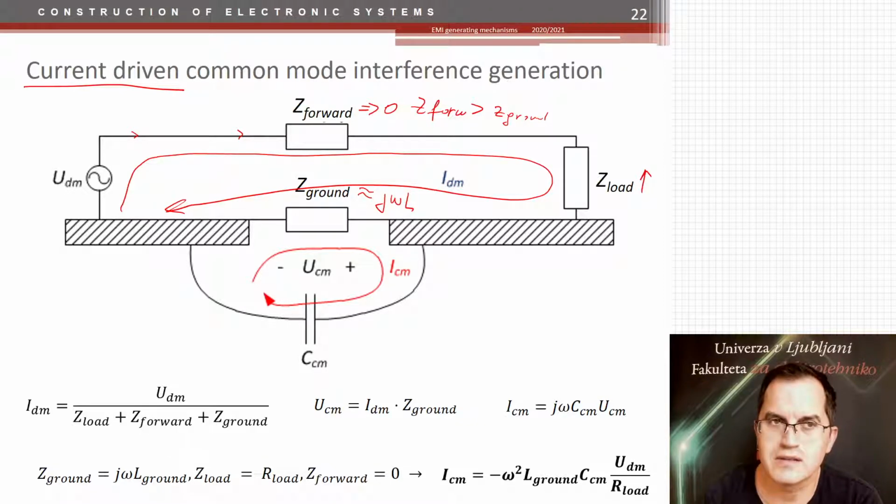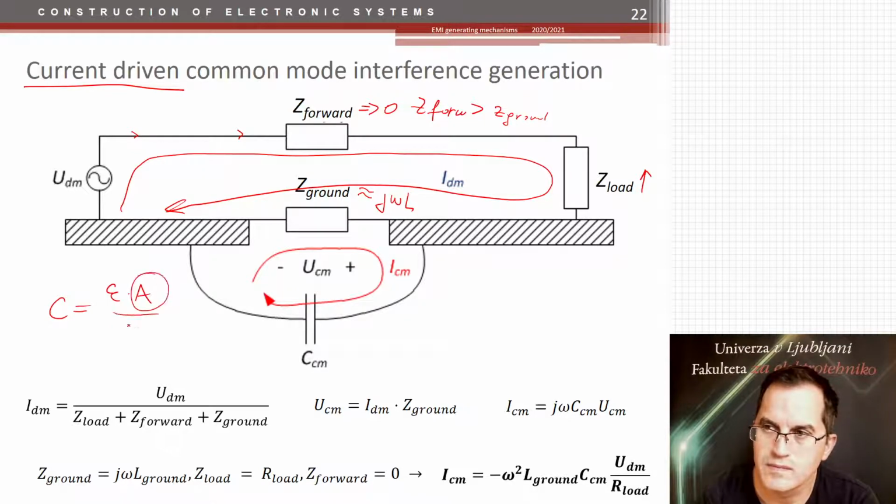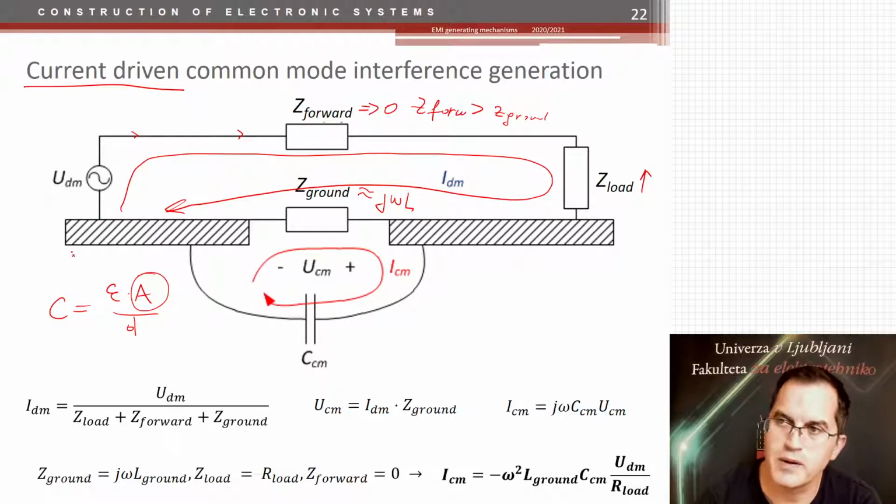And this ground, because it is forming a large area, has a nice capacitive coupling because the areas of the capacitors are large. Therefore, this capacitance through the ground, from different parts of the ground through the air, is representing a common mode noise path. The third path, which I was talking about.